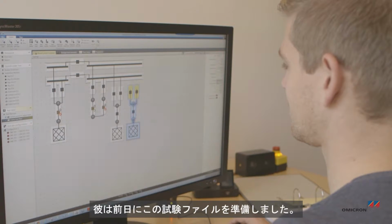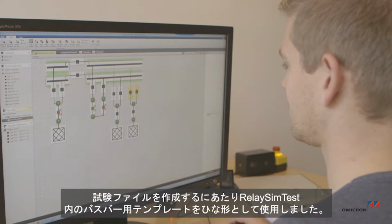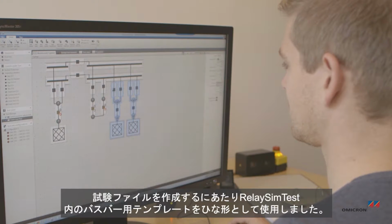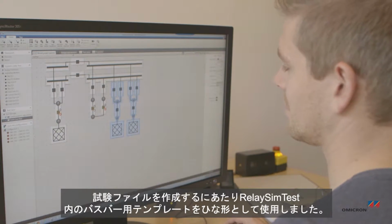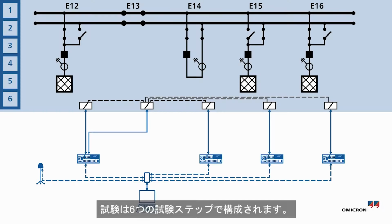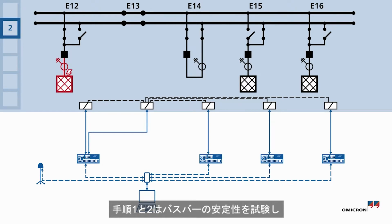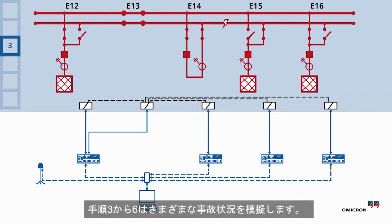He prepared this test the day before. The test models the bus bar topology within RelaySimTest. The test comprises 6 test steps. Steps 1 and 2 will test the bus bar stability, and steps 3 to 6 will simulate various fault situations.